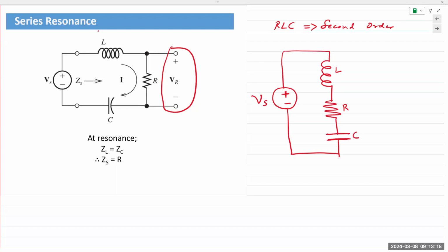Okay. Now, inductors and capacitors are duals of each other. They're very similar in property as well as exact opposite in many cases, right? The opposite refers to the phase or the phase angles of the capacitors and inductors. Now, I always talk about how these are energy storage devices, right? So if you apply a constant DC voltage that flows in one direction, the energy flows into the component. And when the source is reversed or removed from the circuit, then the energy flows back out of these devices back into the circuit.